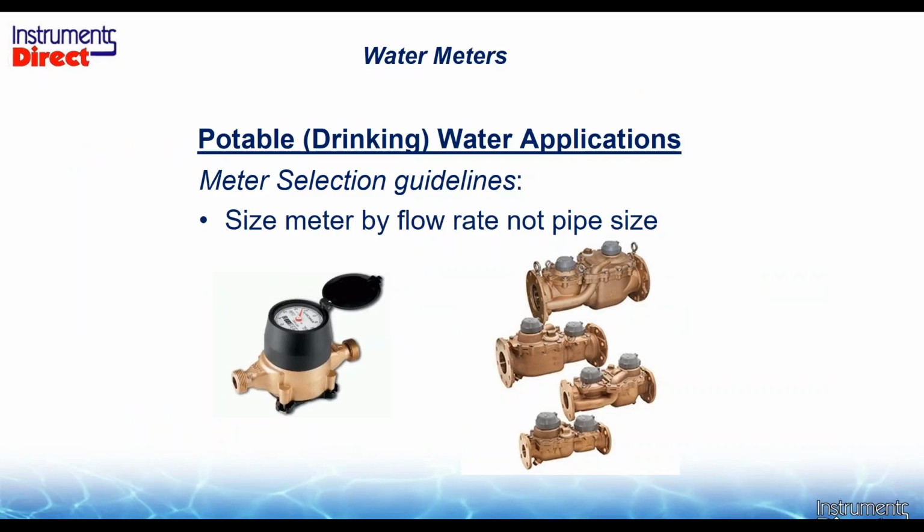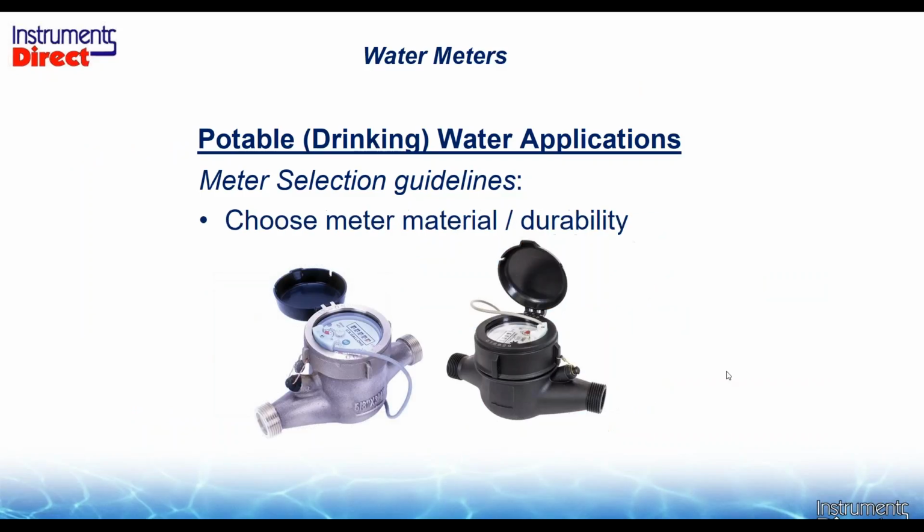Again, we need to size the meter by the flow rate and not the pipe size. Hence, you see all the different pipe sizes that you can possibly have here with the water meter. And over here, we're moving over to water applications. We need to choose the material for durability and compatibility, the material compatibility situation.